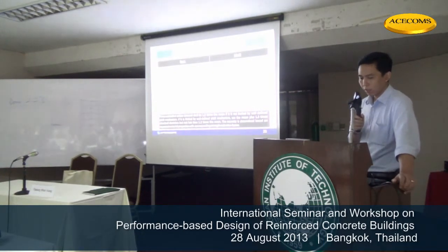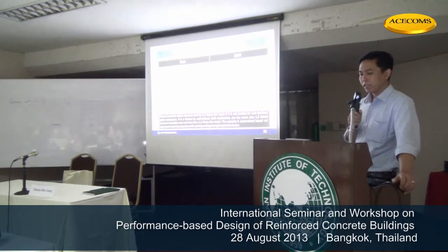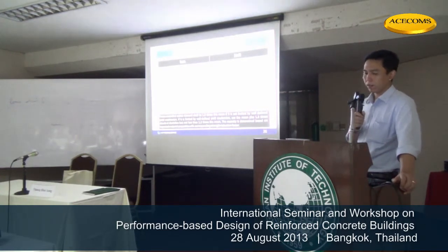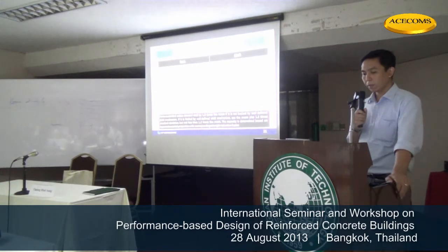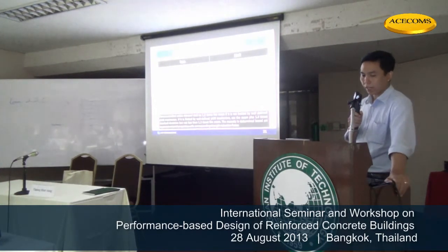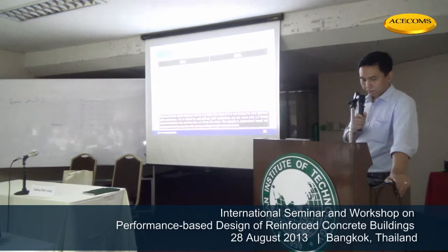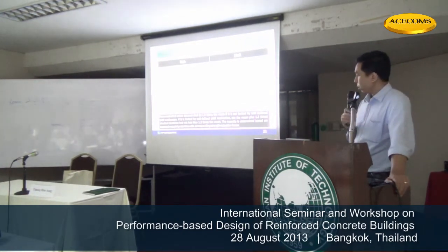For the preliminary design, using design basis level, we normally use the response spectrum analysis. We do not perform the nonlinear analysis. We use the site-specific elastic response spectrum, and then we design the building according to the code.